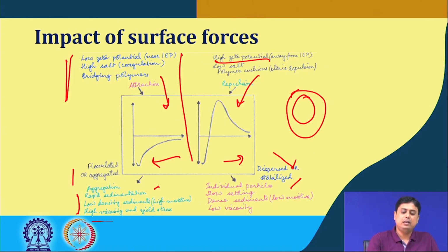So, that results in individual particles, low settling rate, dense sedimentation or low moisture content, and a low viscosity suspension or material. So, this is how the solution property can control the attractive or repulsive nature of the force, and how this attractive and repulsive force is then translated into the solution behavior, the suspension behavior or the fine particle behavior.